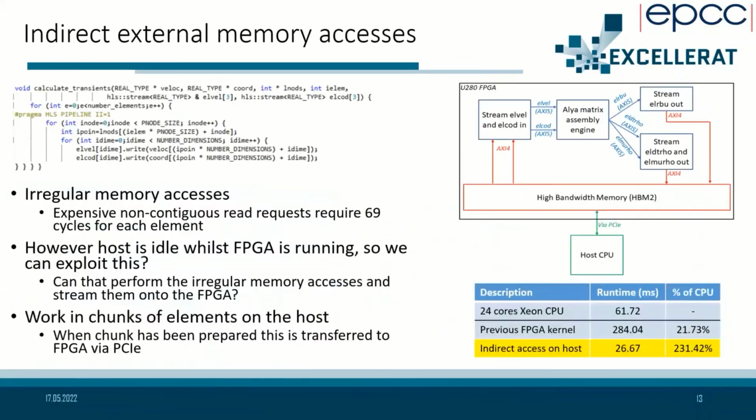And here the big challenge was actually how we were feeding data into the FPGA. And we had to move quite a way away from what we'd assumed initially and do quite a few enhancements around the way that this is working with the FPGA in combination with the host to work in different batches to again keep the electronics fed with data, this golden rule of keeping the data flowing through.